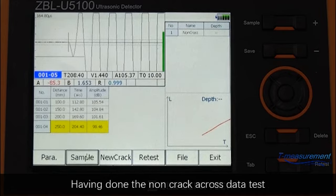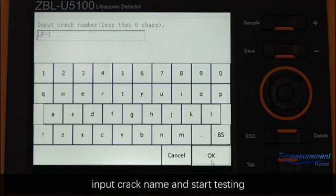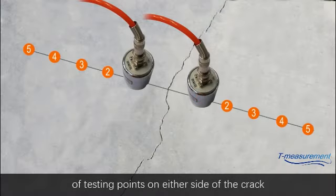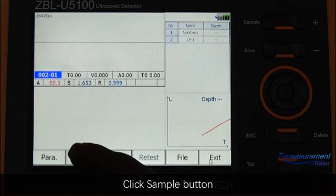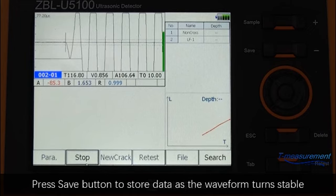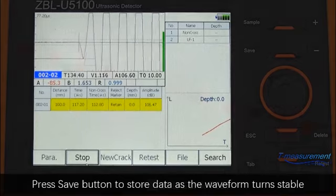Having done the non-crack cross data test, click New Crack, input crack name, and start testing. Place 2 planar transducers on the first pair of testing points on either side of the crack. Click Sample button, adjust the waveform to make sure head wave appears on the screen. Press the Save button to store data as the waveform turns stable.